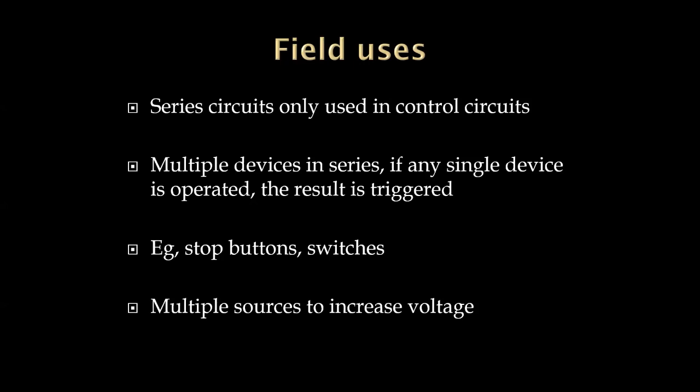Okay, I don't want to have to go down to the bottom of the stairs, turn that switch off, and then go all the way to the top of the stairs and turn that switch off before the light turns off. I want it to be any one. So it goes back to the second statement: if any single device is operated, the result is triggered. Okay, stop buttons and switches.